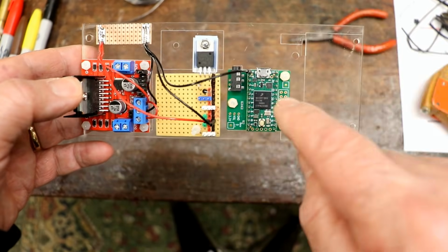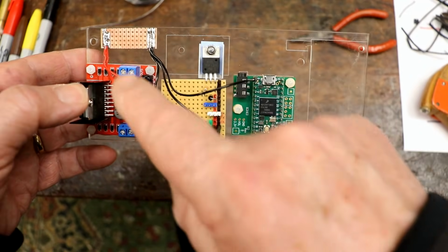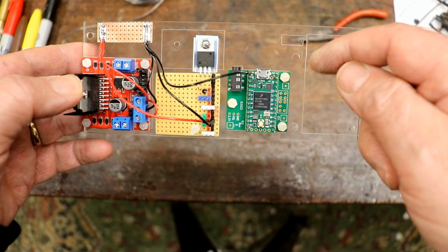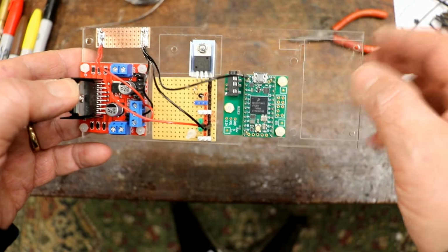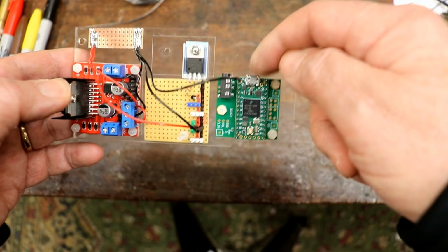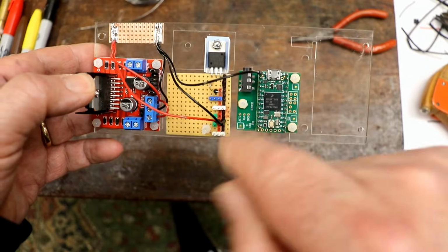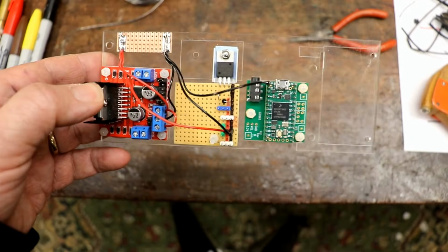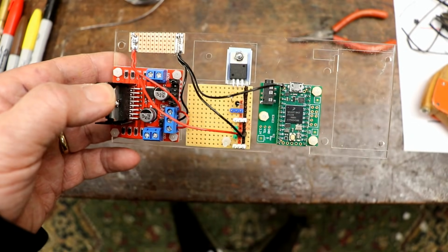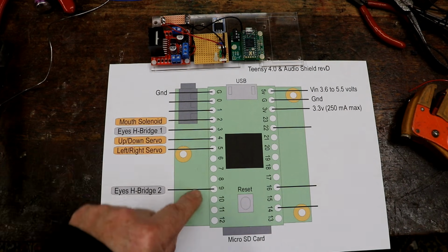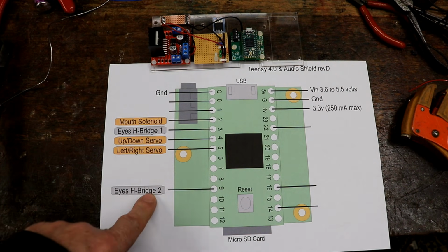Everything is grounded out. We're not going to run this from 5 volts from there at the moment, because while we're programming it and setting it up, we want to run it off the computer. So the USB lead, when it's plugged in, will run the Teensy, and that's absolutely fine because everything's grounded, so the electricity can control everything easily, if that makes any sense. So now I'm going to wire up the interfaces to these 5 outputs.